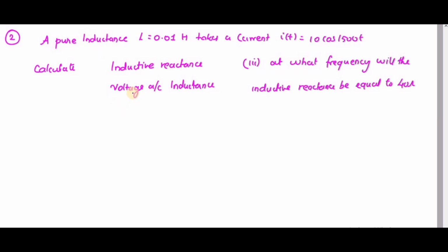The inductive reactance XL is equal to omega L. The omega value is 1500 into 0.01, that is equal to 15 ohm.